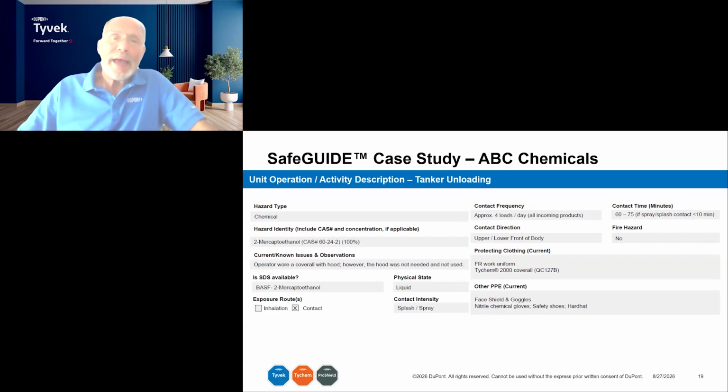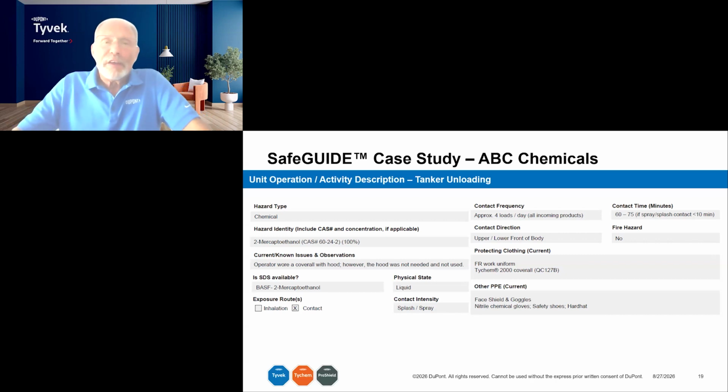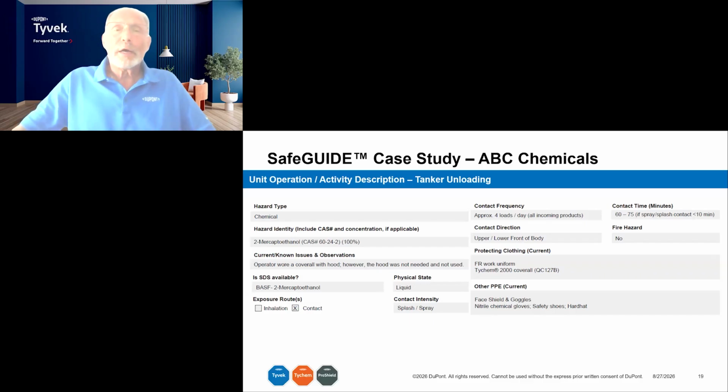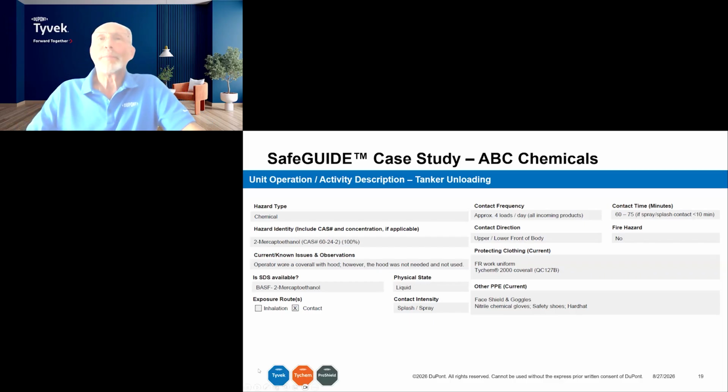And again, we had a Tychem 2000 coverall over the top of that. Additionally, face shield and goggles. Again, no respirator because there was not an inhalation concern. Gloves, chemical gloves, safety shoes, and a hard hat. Okay.